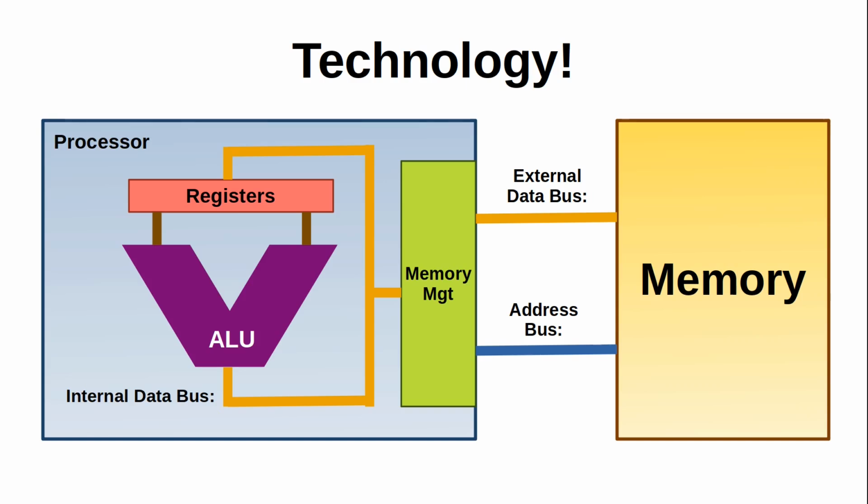So where do we draw the line? What part of this whole architecture needs to be 16 bits for it to be a 16-bit processor? Well, like we've already said before, it's not the address bus. The 6502 and the Z80 both have 16-bit address buses, but they are certainly not 16-bit CPUs.